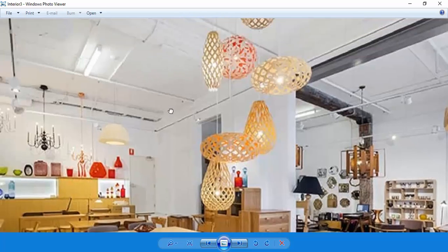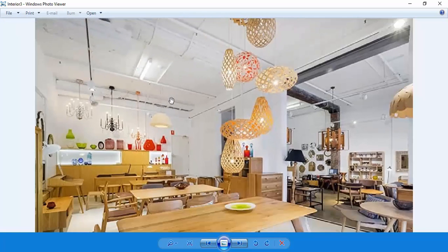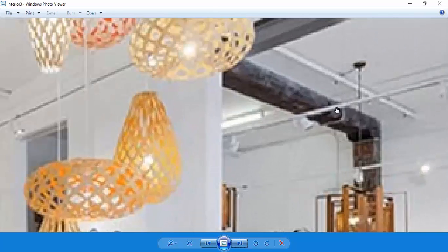And one option for your designs might be to remove that ceiling lining and have the floor joists exposed, and you could easily model in the floor joists and have them as a nice feature that you'll see in your perspectives. And if you're going to do that, then the floor joists need to sit on top of your beam. So you need to allow space for that.